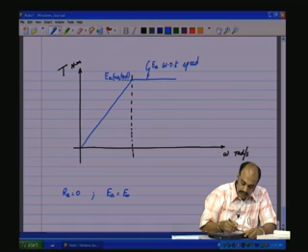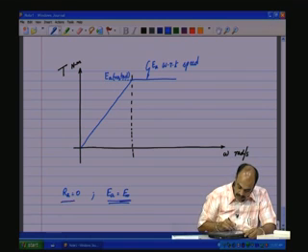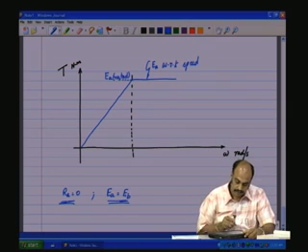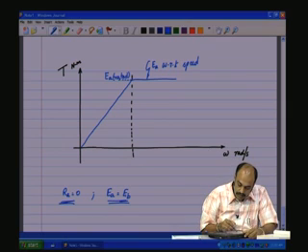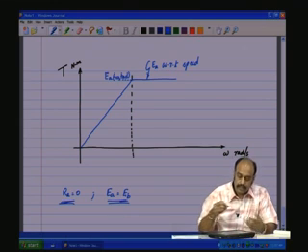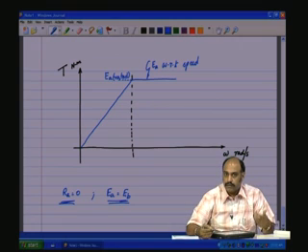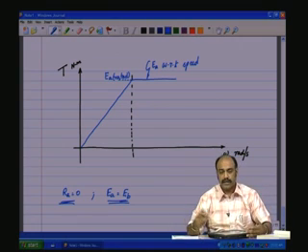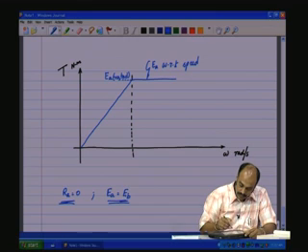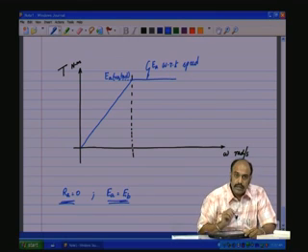So, this is actually the back EMF also, EB, because RA is equal to 0. Beyond a particular speed, the back EMF has reached the same value as the rated voltage, and we can't apply a voltage more than the rated voltage, otherwise the machine will saturate. So, it has to get clamped beyond a particular value of the speed.